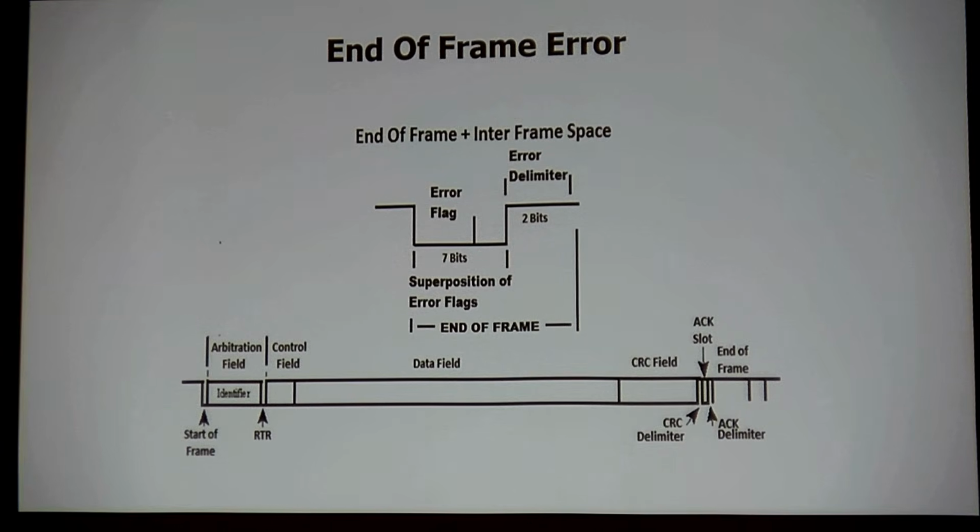We got an RTR. That's the end of that portion, and now we start the transmission. And that message transmission is who is doing the cyclic redundancy check, isn't done on the front part of the message, right? It's only done after RTR. Now I look at the message, and the message came up wrong, and I'm another module. You're broadcasting that message. I'm another module. I ran a CRC, and I think you're bad. Well, it didn't come up wrong because it's bad. It's because my timing edges are messed up. I'm not in time with the bus anymore. And now I go and I destroy your message by putting a bit there. Everybody says it's a global error, and you get a count against you.